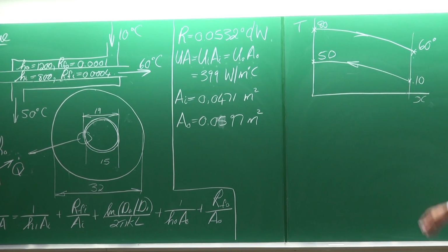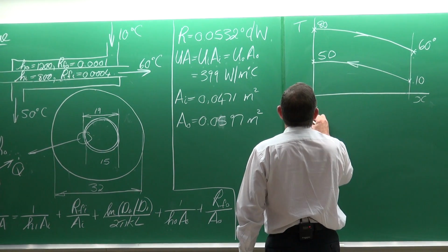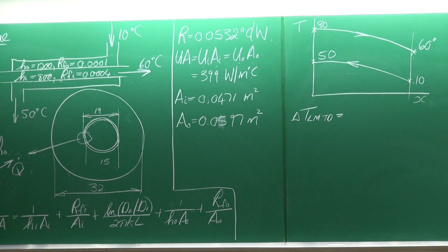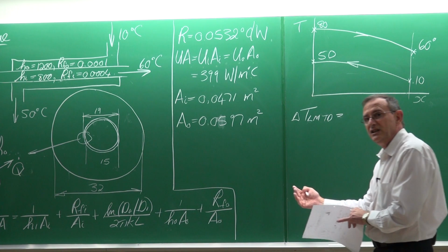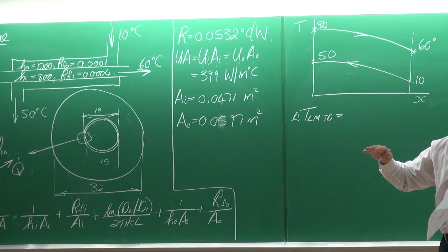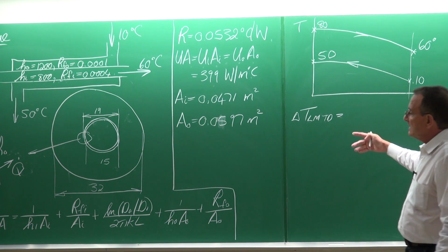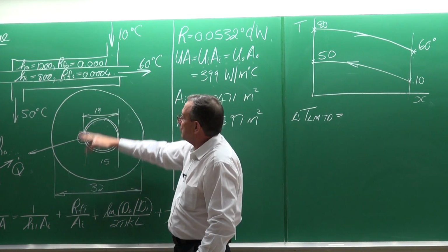So with that temperature distribution, we can calculate the LMTD. And in heat exchangers, as I discussed at the beginning of this lecture, what is different from this chapter than other chapters, typically the chapter that you did on internal forced convection, where you could have a wall with a constant heat flux or a wall with a constant wall temperature, is that in this case you've got two different streams separated by the wall.